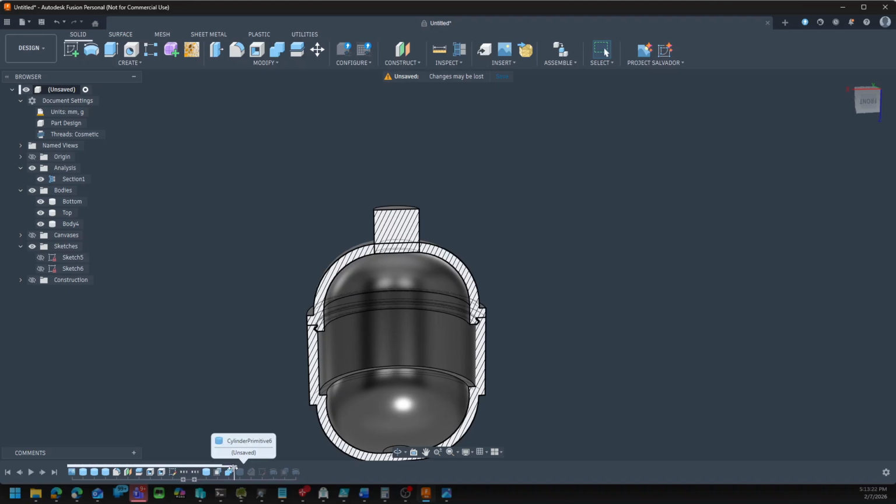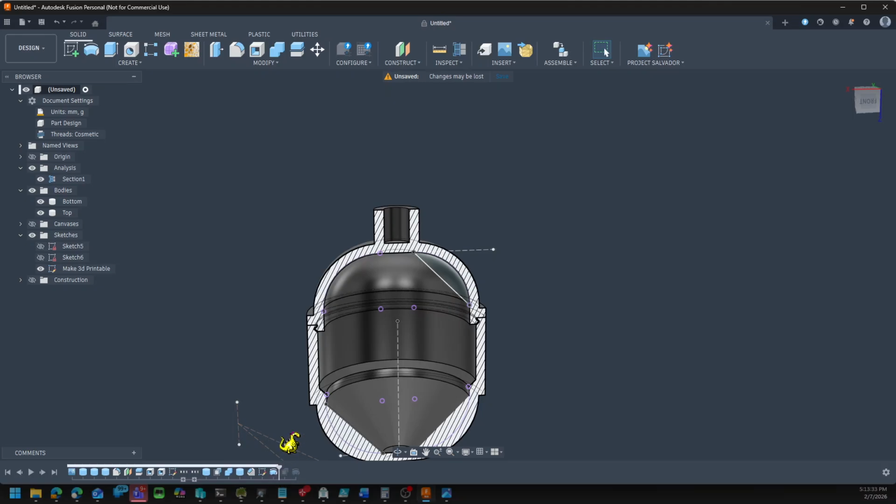Combine. Punches a hole in it, that's good. Modifying the top seems to go okay. Oh, but modifying the bottom doesn't. Well, that's crap. All right. So, looks like you need to go back, and this sketch needs to happen earlier in the timeline.